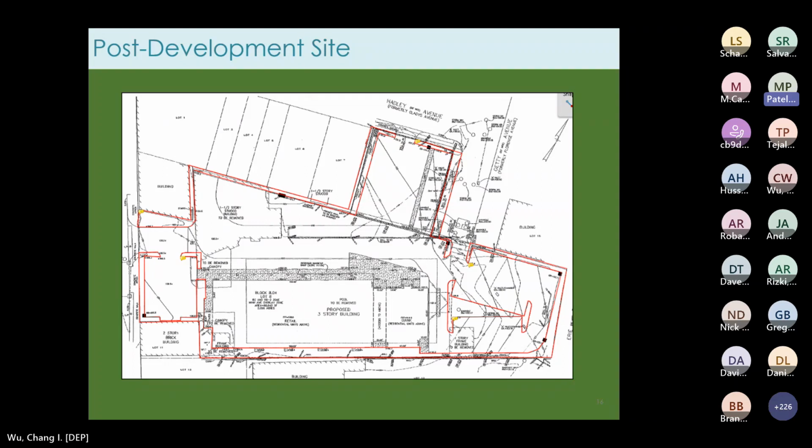Then what ended up being proposed was a 3-story building. And if you identify around the property lines, a fairly big island in the parking area towards the right is where they're identifying their pervious areas. So based on the information that they have given us through the designs and reports, we understand the total disturbance is at 2.13 acres. The increase in impervious areas is going to be slightly less than the quarter acre, as we discussed earlier.